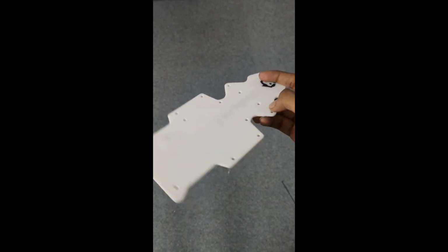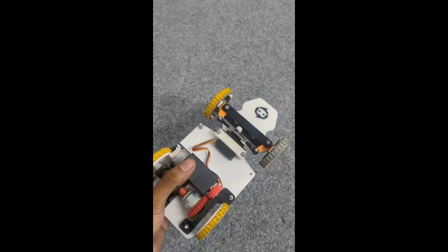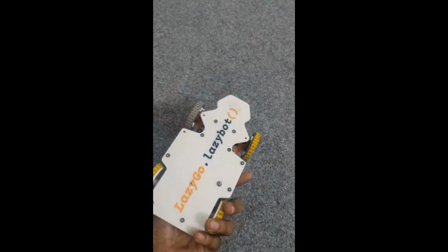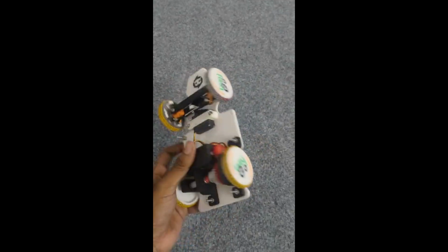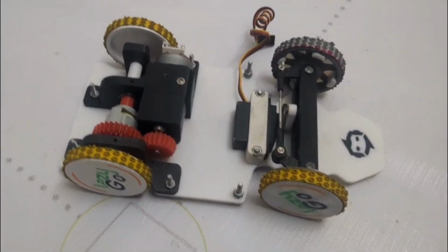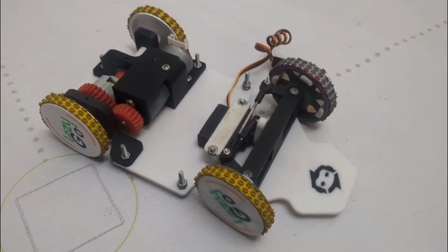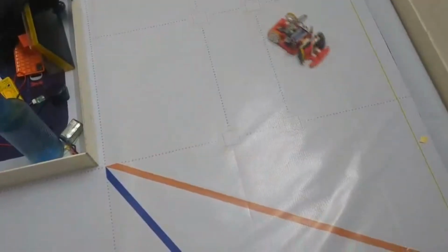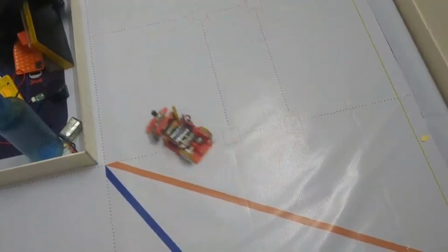Then we 3D printed the base, the steering mechanism, which you can see here in action, the motor mount, and all the other parts. A huge thanks to bot engineers for printing these beautiful multicolor parts. Well, this can also be printed in single color. Anyways, we are using an Ackermann steering system and a differential gear system for our robot, which allows it to take really tight turns. Now, this was the turning radius of our robot previously, and this is how it works now. Let's see how we assemble all the parts.